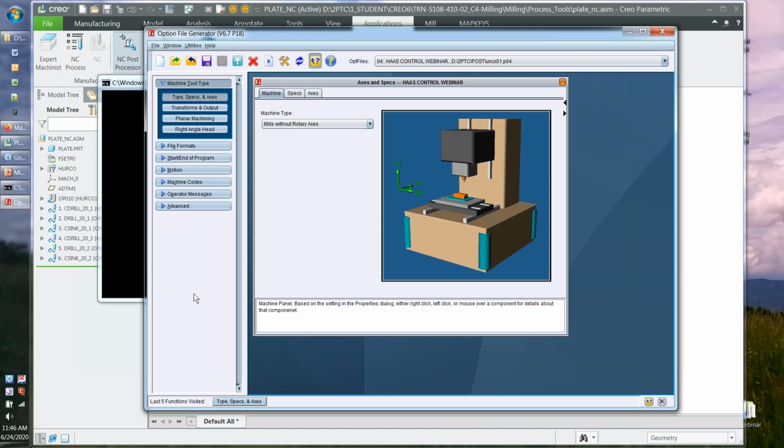That the rules of what must happen in the context of creating a post processor, and this is no different than GPost or any system, those rules are defined by your machine tool. The programming manual for that machine tool, the G&M code manual, and its day-to-day operators are immensely invaluable in the context of being able to create a post processor that works for your client, which is that day-to-day operator, as well as something that the machine responds to correctly.